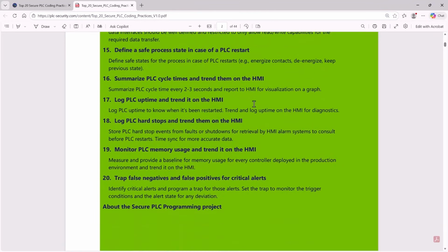Again, it's always about understanding these different vulnerabilities, not just accessing the PLC remotely over the network using an unauthenticated protocol like Modbus, where we can make changes to what's going on in memory, even though, yeah, that's definitely a significant vulnerability. But what about vulnerabilities that exist in the firmware? Remember, the operating system of that PLC, or in the code, the logic running on the PLC itself.